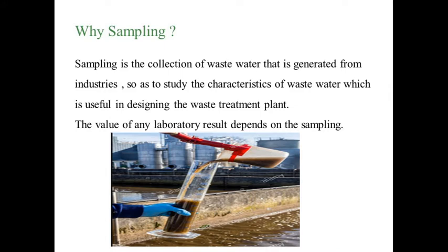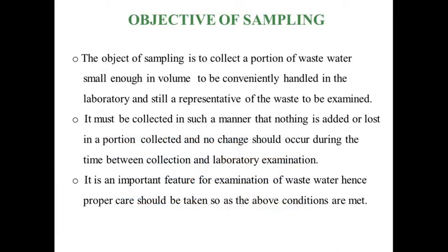So sampling is defined as the collection of a wastewater sample generated from industry so that we can study the characteristics of the wastewater, and from that we can design an effluent treatment plant or wastewater treatment plant. The object of sampling is to collect a portion of wastewater small enough in volume to be conveniently handled in the laboratory and still representative of the waste to be examined.